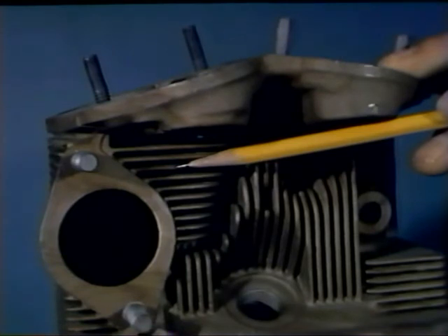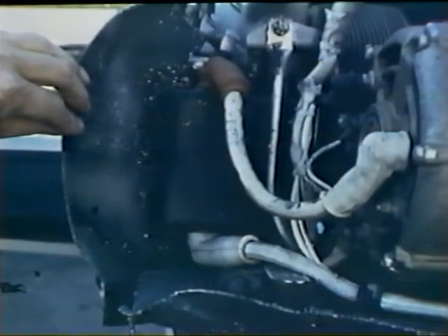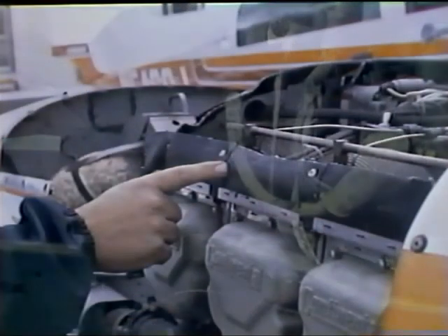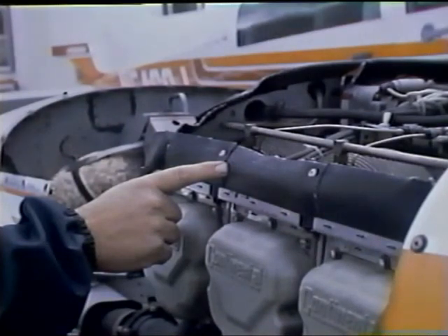Around areas of the cylinder that have an excessive amount of heat, such as near exhaust valves, the fins are made extra deep to provide more surface area for cooling. To force air to flow through these fins, intercylinder baffles made of thin sheet metal are installed. And seals prevent air from escaping any other way.